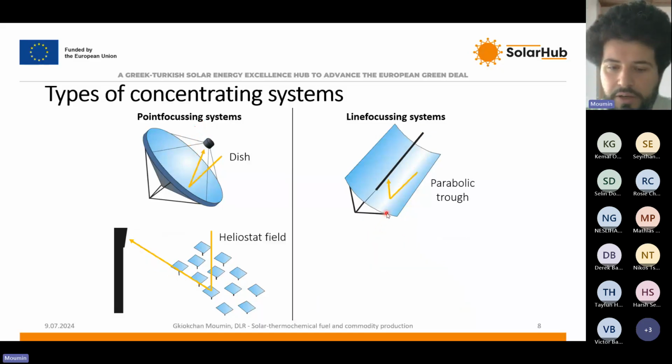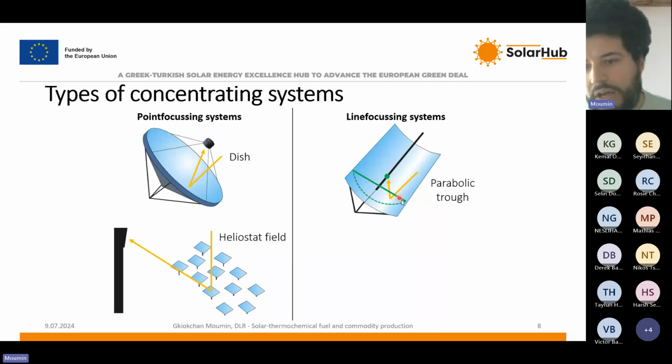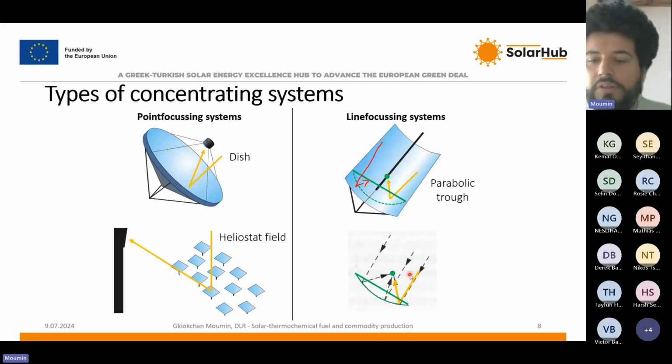Okay, if we again apply now this concentration factor that I've mentioned before, for that we have to observe it in a bit more abstract way. If we draw here the concentration line, this is where all the radiation hits the mirror. So in the solid gray line, all the radiation entering through the solid gray line from the top is absorbed, and if we assume it's absorbed on the spot, these are the two ratios of these areas, basically. If we watch this from the side, this is how it looks. We have the sunlight entering, and all that enters through the solid line is then focused on the spot.